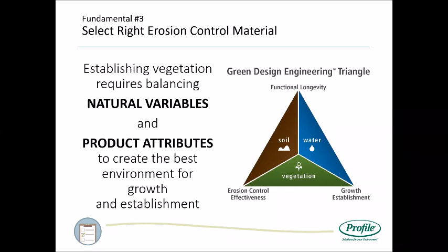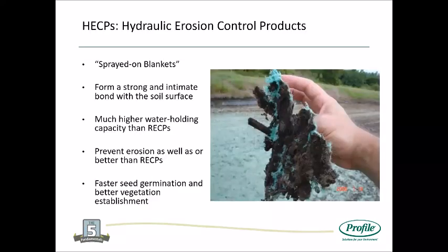It does a very good job of keeping the soil in place, but nonetheless, we are just moving that water downstream, heating it up, and completely disregarding vegetation on your site. So really it's all about those balances that are going to lead to sustainable vegetation, and oftentimes what we're looking for on our sites. We don't want to concrete over every site that we run into just because it's great erosion control. All right, so hydraulically applied erosion control products.